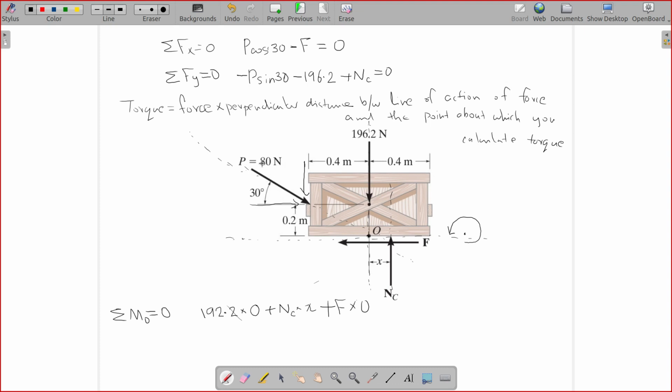So it's easier to split P into two components. We have already done that. You can split P into 80 sin theta, which is acting downwards, and 80 cos theta, which is acting towards the right. That will be easier because we can very easily find the distance between these forces. P is the only force remaining to be dealt with, and we are splitting P into two parts.